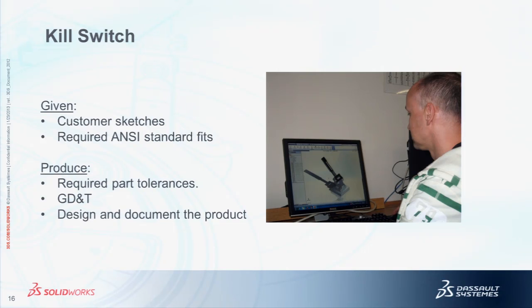I have seen where people have come up and said, SolidWorks is screwing up. My installation is bad. I take this view and I project it off here. It's the wrong view. I said, you're using first angle. How did you click on that? What template did you use? So it's kind of funny that you mentioned that, because it is out there.